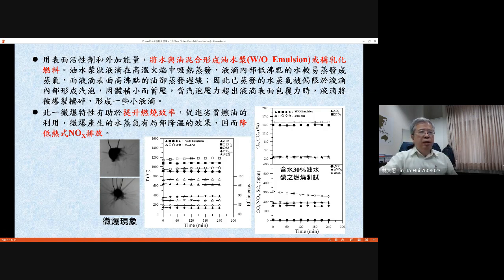At the spray, the temperature is not too high, but at R7 they go to the main combustion region. The temperature goes to the highest position, then it reduces continuously after R7. The diamond symbol represents the temperature of the flue gas emitted out. And the star symbol represents the efficiency we estimate based on the excess oxygen we have in the downstream region.